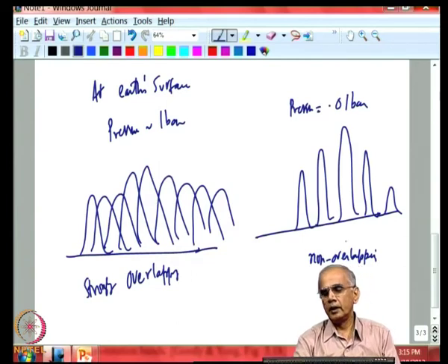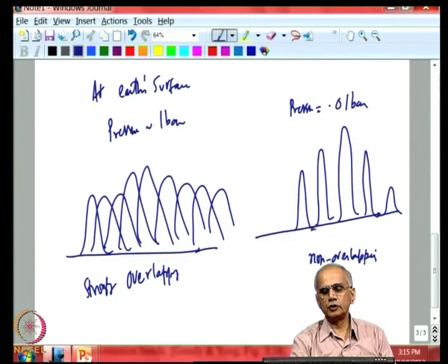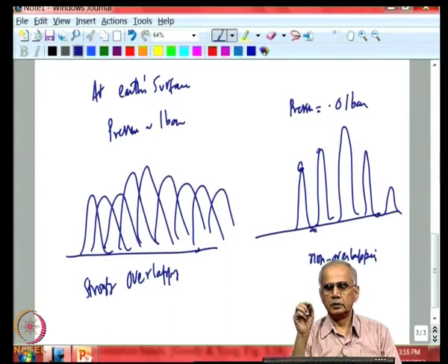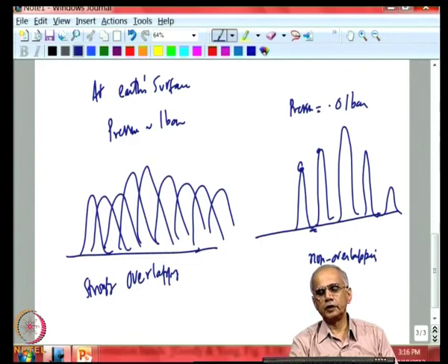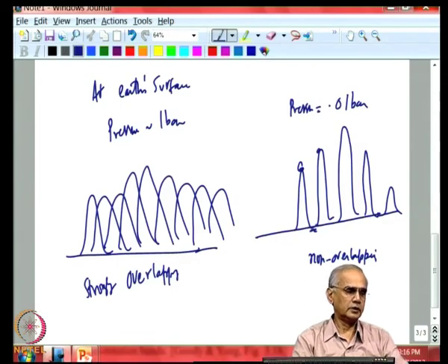On the other hand, if the lines are non-overlapping, you will have great difficulty in integrating the equation, because between the lines there is no absorption, then suddenly absorption gets a very high value. But this does occur with many gases, that there is a strong variation of the absorption coefficient with wavelength, but this is an unavoidable condition that we have to deal with all the time.